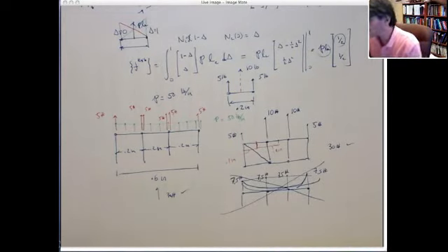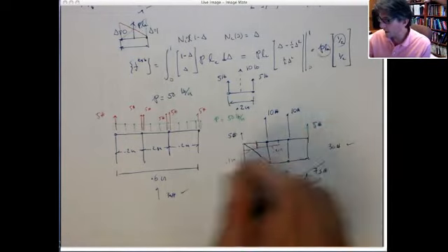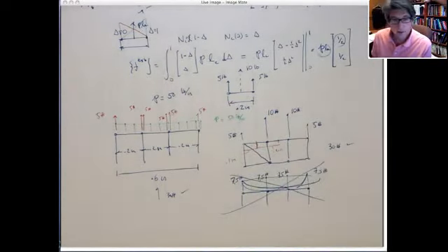Okay, that's actually not technically correct, and I'll show that in the next video when we have higher order elements. But for elements where you have linear interpolations on the edge, like this one, constant strain triangles or Q4s, that's appropriate. Okay.